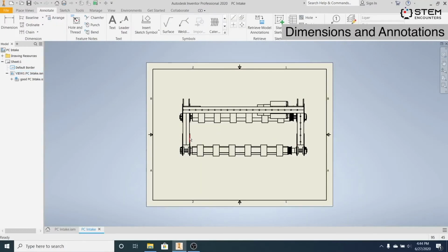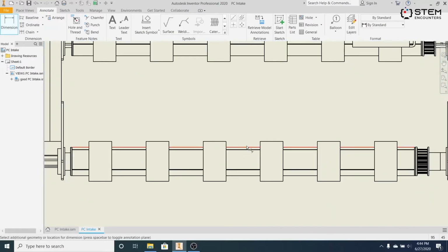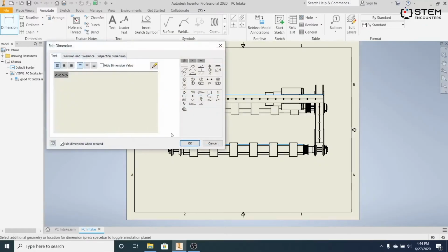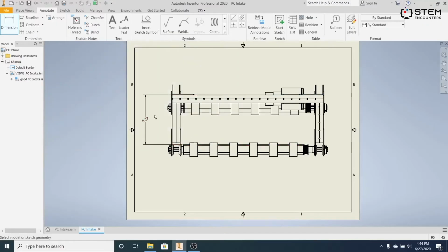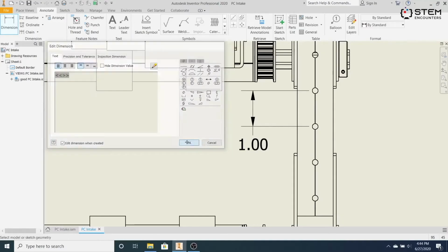The next step in making your drawing more useful for people to recreate your CAD work is to add dimensions or any other annotations. To create a dimension, go up here in the Annotate tab and click Dimension. Then, just create a dimension between any two lines or any other objects or points, and you'll get dimensions that it'll read out to you and can be seen on the paper when printed. You can create dimensions between pretty much any point. Let's say like two points right here. I can get this to work here, and so on and so forth.